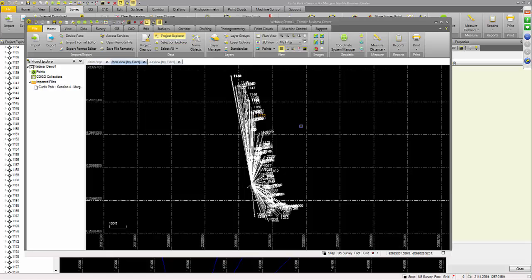So in Google Earth, a good use case is if you, for example, design a static network. Let's use this as an example. In Google Earth, you basically line out your points, how you want your framework to be designed, and you can put in different lines for the different sessions and plot that out and take it out to the field, shoot in your static network.